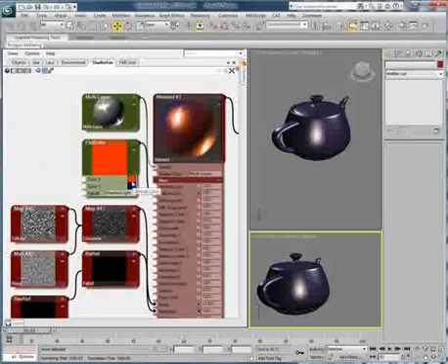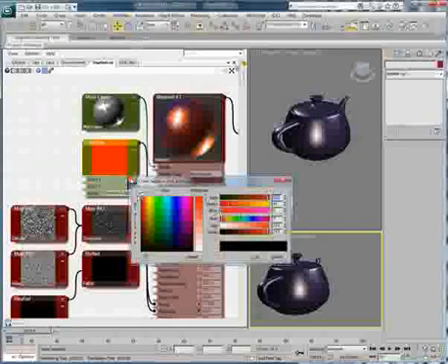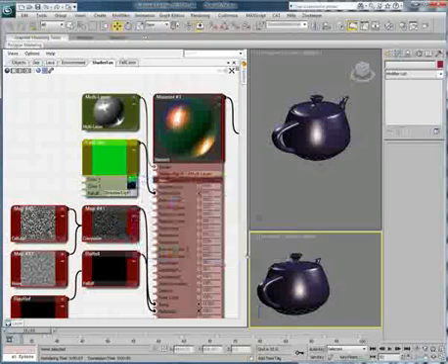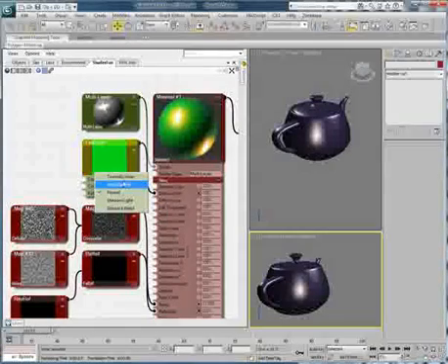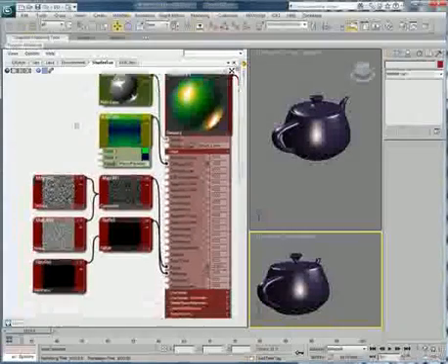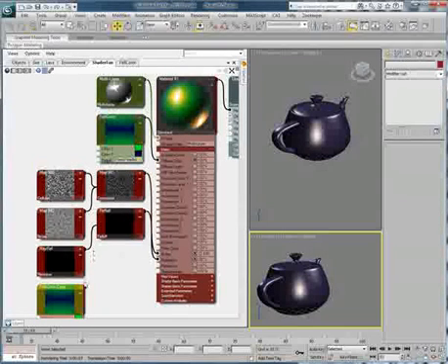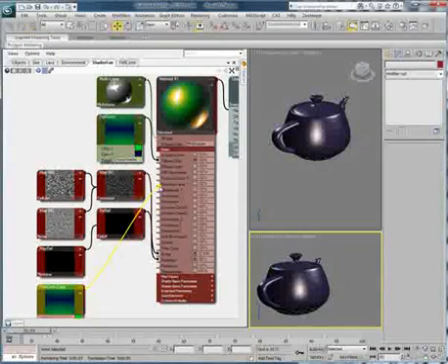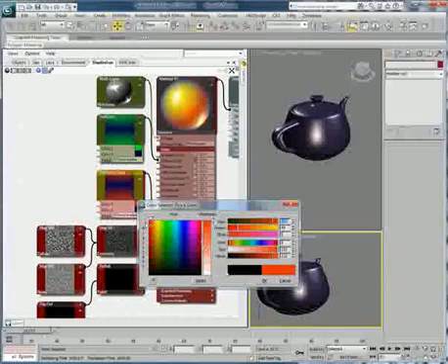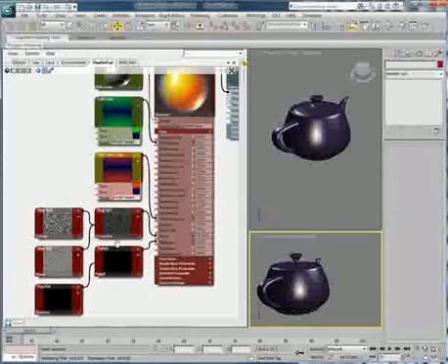So I'll go back here and you'll see that those things are all adjusted here. And they're present in this little node. So I can just change this color to whatever it is that I want. And if I don't want shadow light but I want Fresnel, then I can change it to that, or perpendicular parallel. So that's really pretty useful, because now I can just copy this entire node and I can pipe that into the self-illumination or whatever channel I want. So I'll go for self-illum here, and I have this copy of this little kind of tool node that I've made that really makes it very easy for me to work.